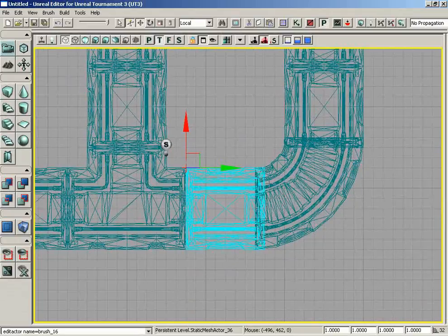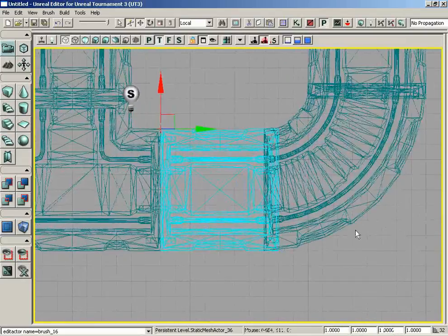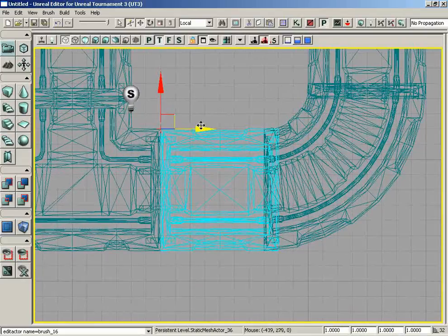Logan, you want to share with us what that is? Well, we need to adjust the scale of this piece. If we change the scale, we could change it so that it lines up. Just for a quick demonstration, you could grab the Draw Scale 3D and change the Y, because looking at the manipulator, you're currently in local space. That's so right. We're looking down the Y-axis of the mesh. So if we adjusted the Y-axis scale using the Draw Scale 3D, like just try 0.5, just some really easy numbers, we can see that we can indeed change the size of the mesh.